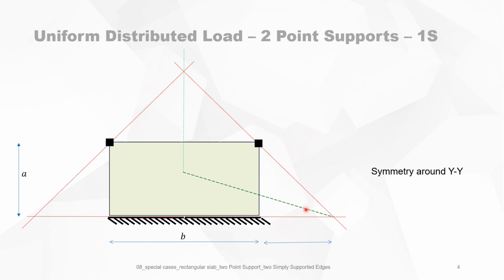The yield line must be situated around this. It's between those two, but we must optimize the angles, alpha and beta, to find the direction of the yield line. You need to optimize alpha to find the direction of the yield line, and beta to situate, in fact, this point.